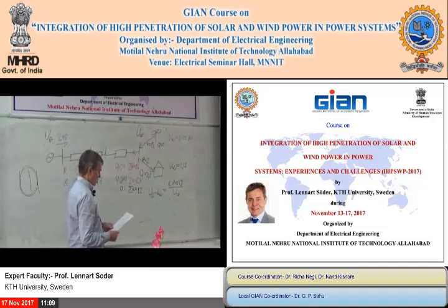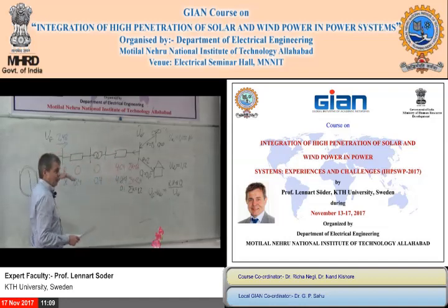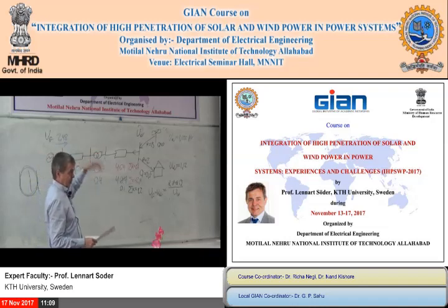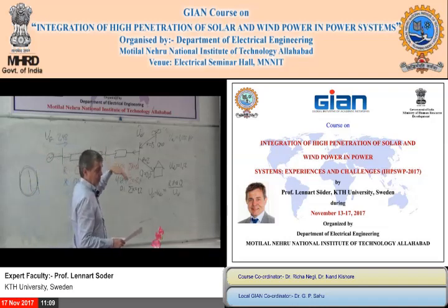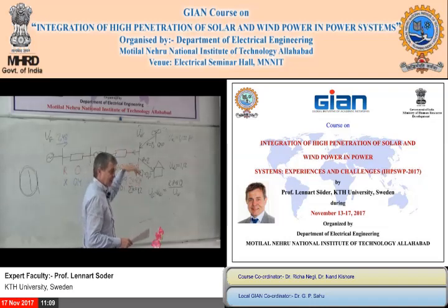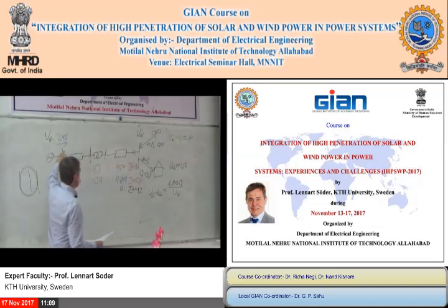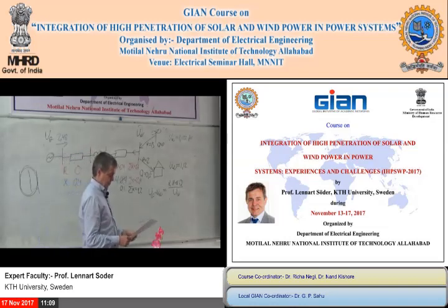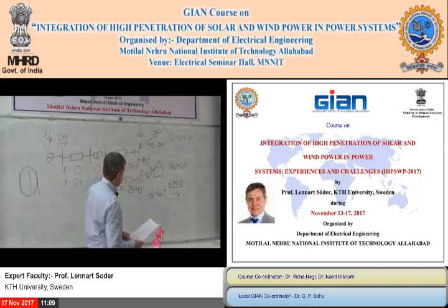Can we now use wind power reactive power? No, it's even worse now, because you have an even higher voltage and you are still consuming a lot of reactive power. You have to consume even more reactive power in order to decrease the voltage. And you will see in the system that you will then increase the consumption even more. That was part 1.